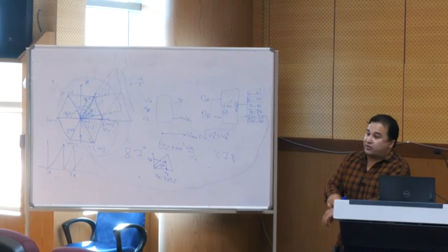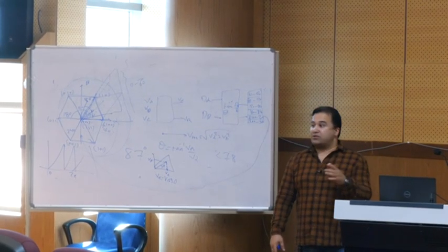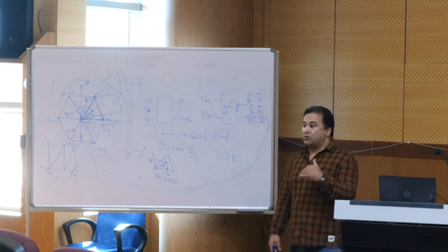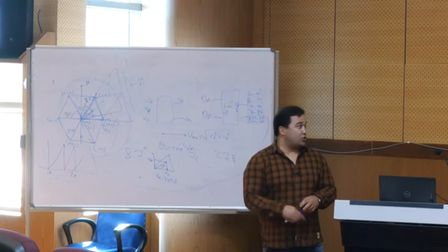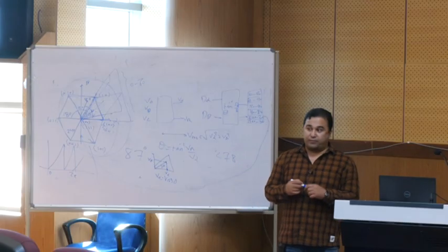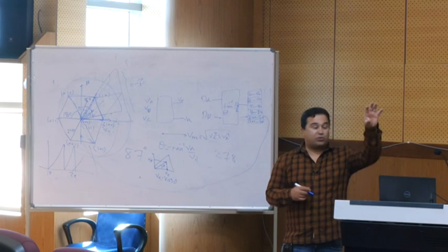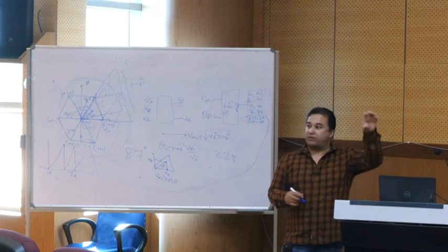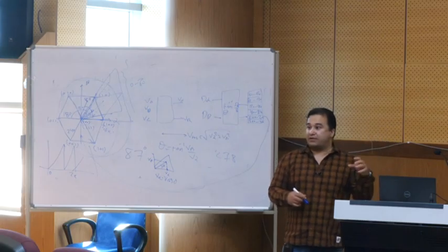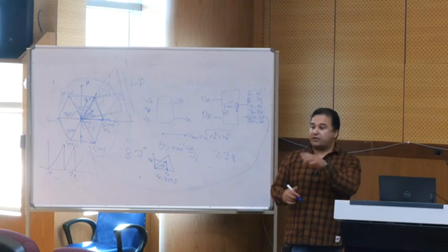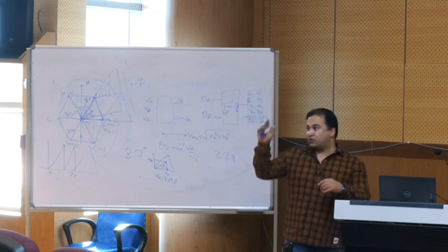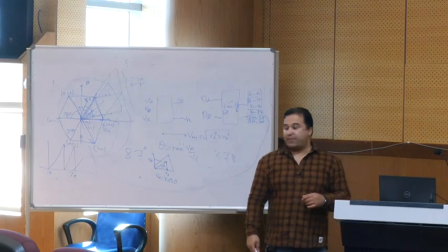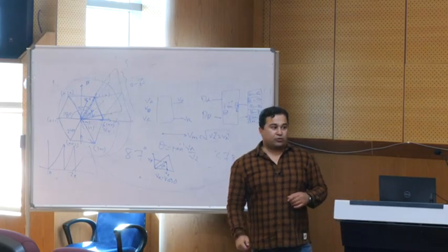But in MATLAB, you easily have access to the block. You don't know what is happening behind it. When you make the simulation, you choose the space vector PWM from the toolbox, put it here, give it the alpha and beta, and see the switch variable. Any questions so far?